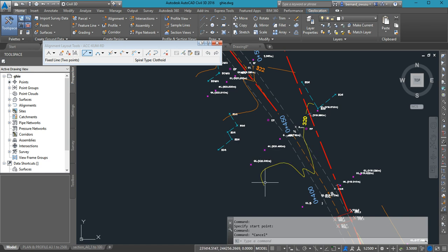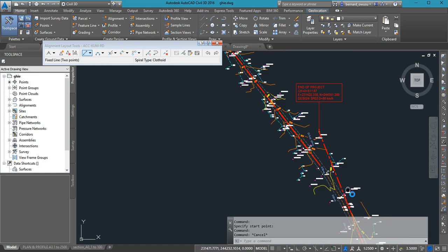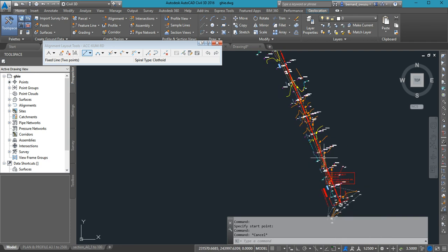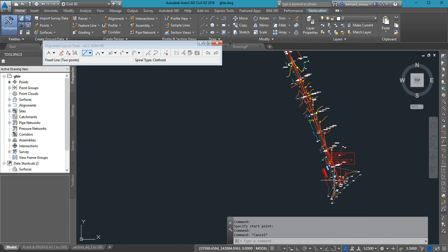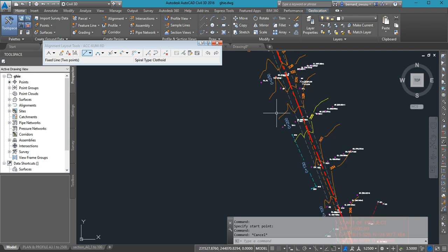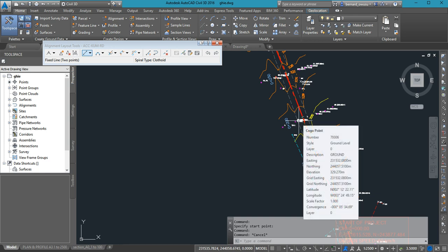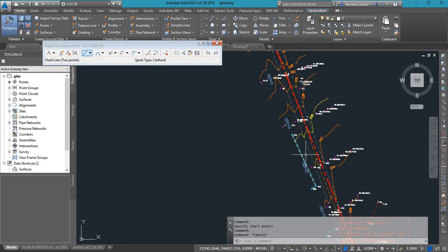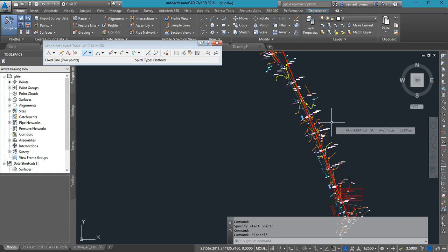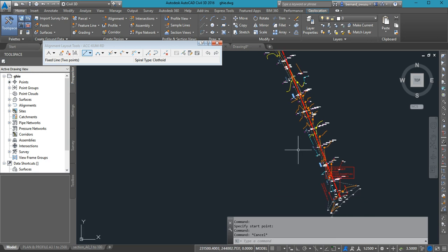I said we are going to create something like an offset. AutoCAD Civil 3D has an option to create an offset alignment. Though you can use normal offset, the normal offset will not be dynamic. Even if you have an alignment from beginning to the end and you offset, if you change the center line, you have to offset again. But with offset alignment it is dynamic. Anywhere the center line will pass, the offset will still be there for you. Do you understand? It's almost like a boundary or a reservation.